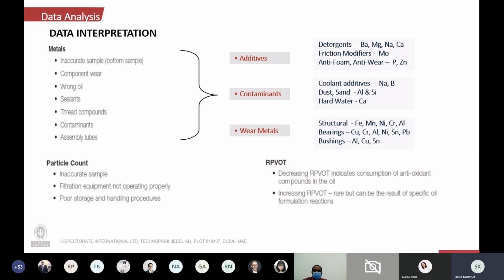So again, in certain oils, like turbine oils, for example, particle count is very important, which is particle sizing. This is done by two different techniques: either laser scattering, which we call optical particle counting, or physical pore blocking particle counting. These are two techniques used in the industry. Of course, the optical one is superior, but it has limitations on the particle size limits or the high levels. But this can be discussed further if somebody has separate questions later on.